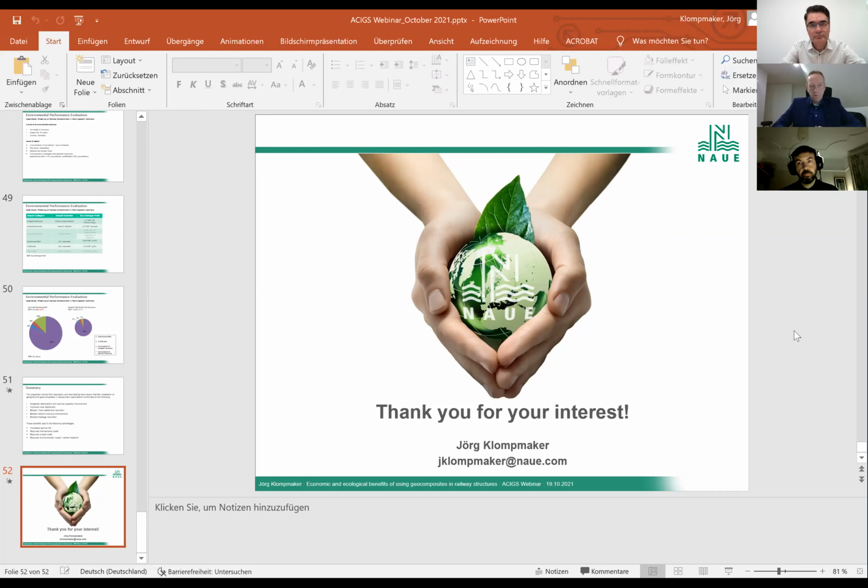And also, just as a rule of thumb, we can say that the softer the subgrade, the higher the strength of the geogrid should be to absorb the tensile forces which are developing as a result of the loading on top. So yeah, the softer the conditions, the more severe, our recommendation is to install a higher strength geogrid, which has more resistance against the deformations.